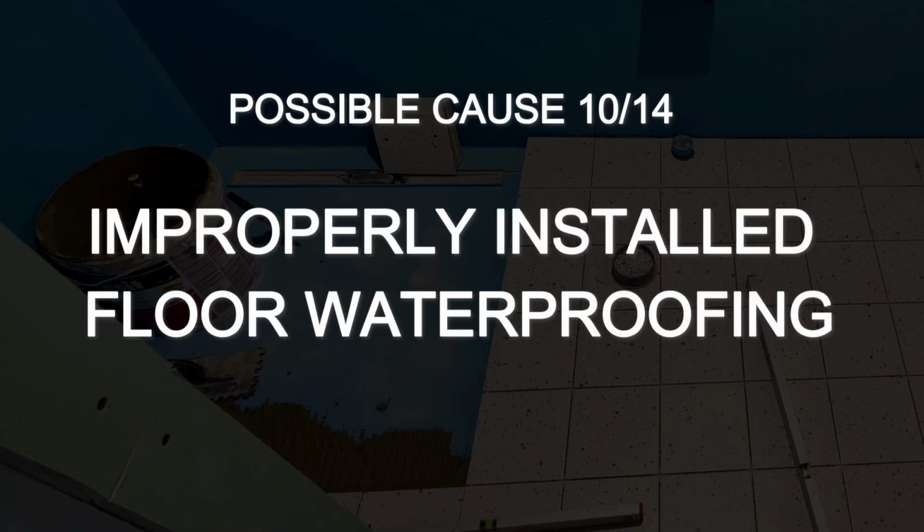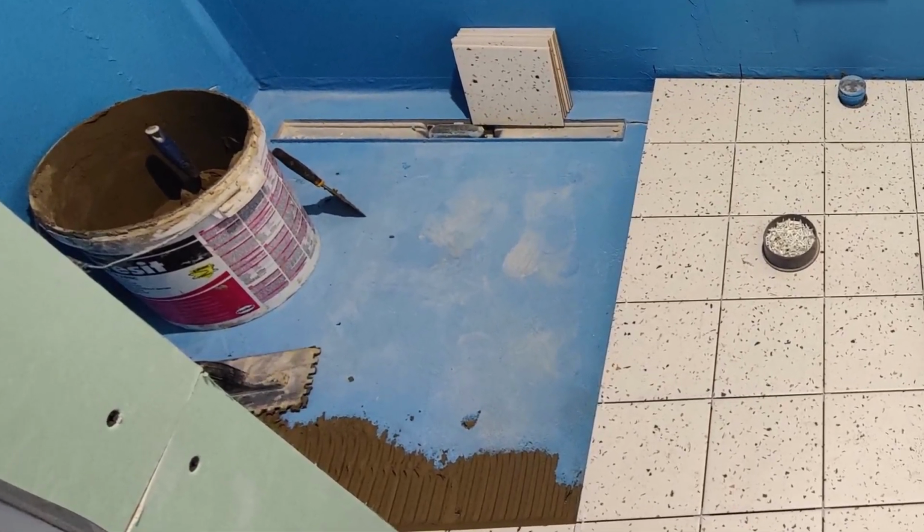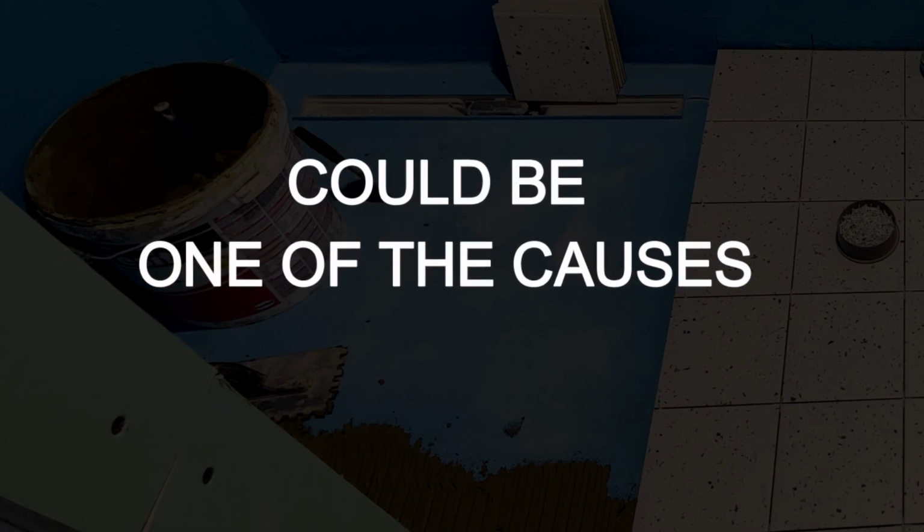The 10th version is a waterproofing layer that is too thin or an insufficient number of layers. Such waterproofing usually requires at least 2 layers and a specified dry layer thickness. In the construction photos, some areas looked lighter, and the documents did not show the number of layers everywhere. It was no longer possible to measure the actual thickness.